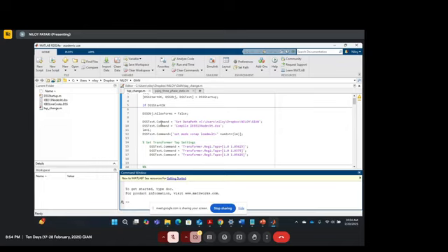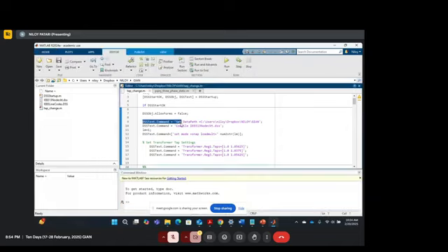In the DSS text command, whatever command you put here, it connects that with OpenDSS. So you set the path or location of the file, and inside this folder we also have this IEEE 13 node circuit.dss. When you say compile, it compiles the whole DSS circuit file.